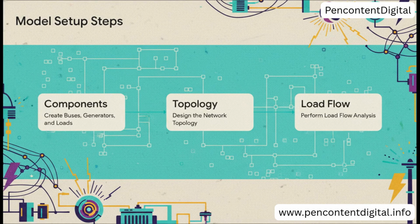First, you create your buses, generators, and loads. Second, you map out the intricate network topology connecting them all together. And third, you perform that baseline load flow analysis. Because, frankly, you cannot run advanced dynamic simulations on a model that hasn't been carefully parameterized and stabilized first.